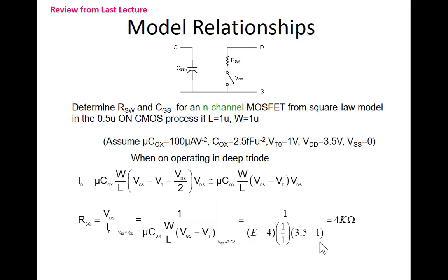Was it acceptable to neglect that earlier? We didn't tell the whole story earlier, did we? We said, let's assume we've got this switch level model for our transistors. We didn't say that there could be different switch level models when you change the dimensions of the device. We didn't say it was going to be different for different processes, but now we see it is, and we see how to move from the process to the switch level model.